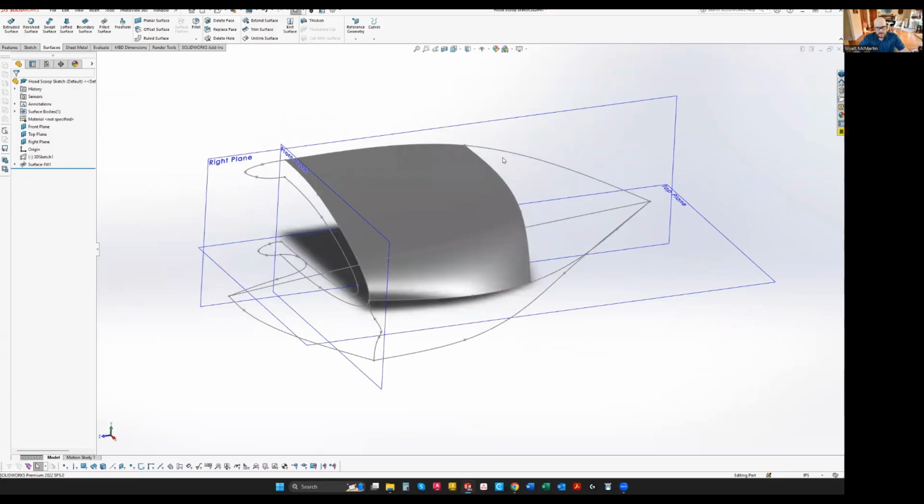Now, I'm going to go ahead and do this triangular panel here, and I'll show you the tool again. And then what I'm going to do is show that you can actually create and isolate all this geometry into individual sketches, and then go ahead and use the tool over and over again, instead of doing each section at once and then creating the surface.